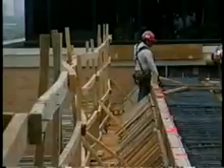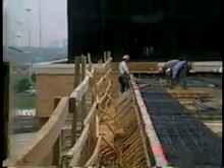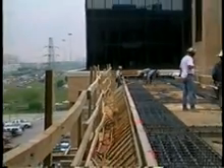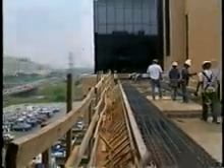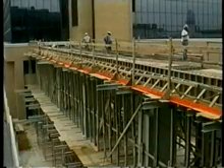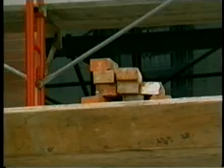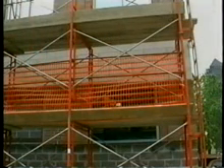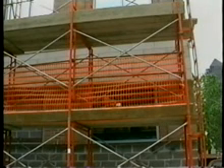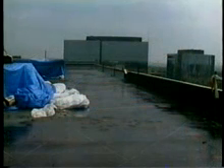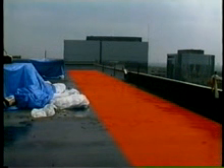Whenever the hazard of falling objects exists, guardrails shall have openings that are small enough to prevent the passage of objects to lower levels. Install a solid panel or screening barrier in the guardrail system. When tools, equipment, or materials are piled higher than the top edge of the toe board, paneling or screening shall be used from the walking or working surface up to the mid-rail or top rail as appropriate. Materials shall not be stored within 6 feet of a roof edge or open side unless a guardrail system has been erected at the edge.